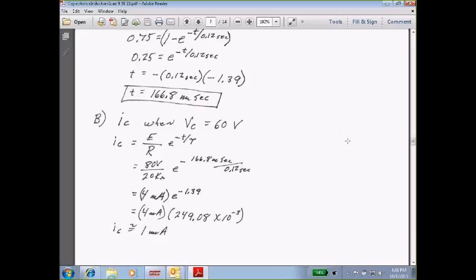Well, if you just hooked a battery up to that light with a flasher, you'd be changing the battery every day. One night you'd run the battery down. But what we do is we put up a circuit that's got a capacitor in parallel with an inductor, so that the capacitor's charging, and as it discharges, it goes across the inductor, and then the induced voltage from the inductor charges the cap, and they just sit there and trade back and forth.